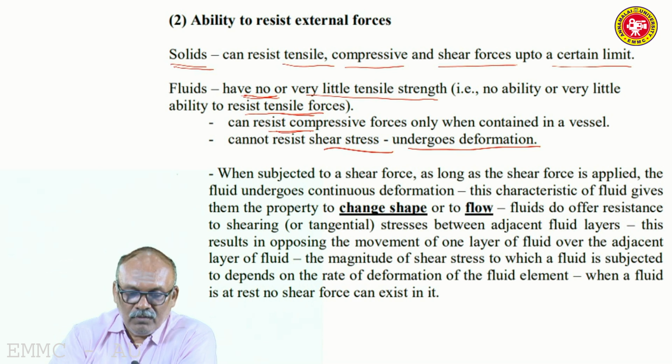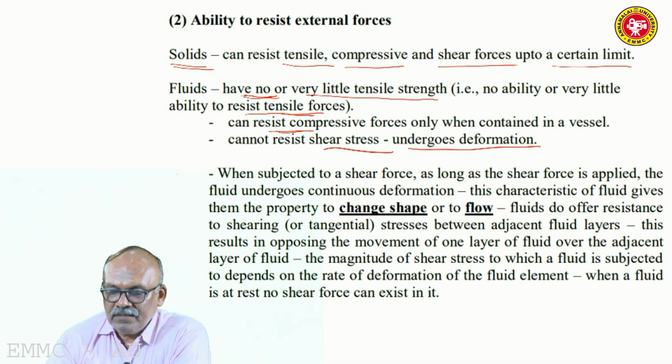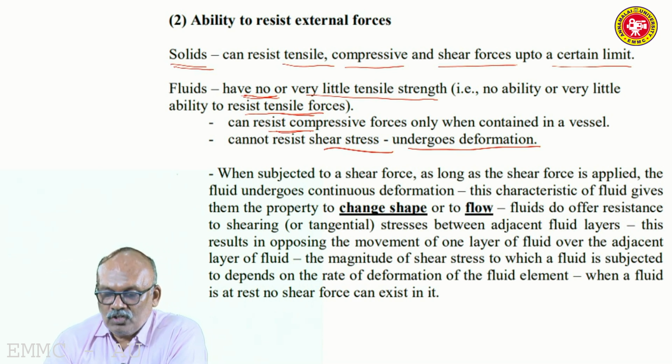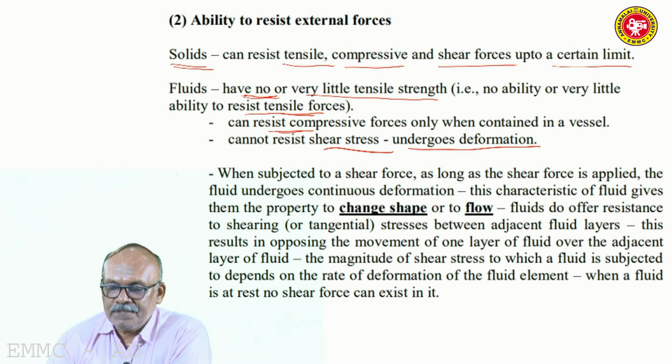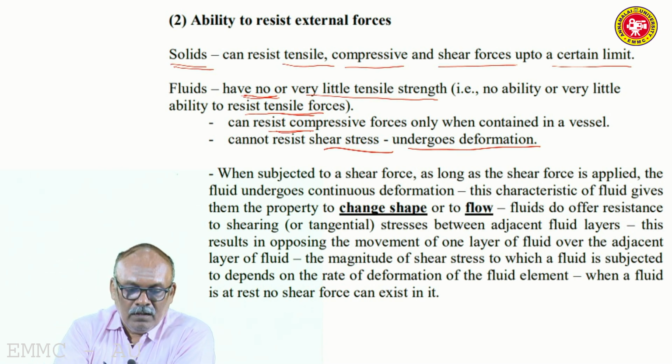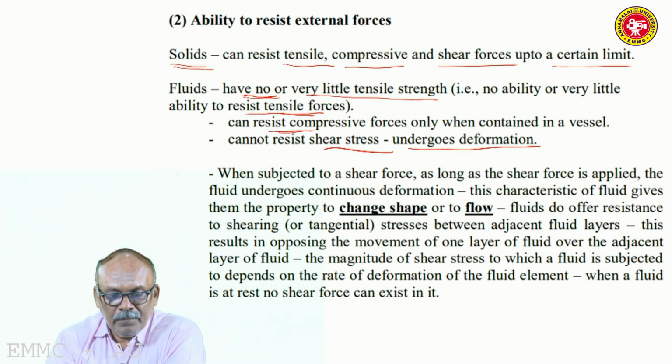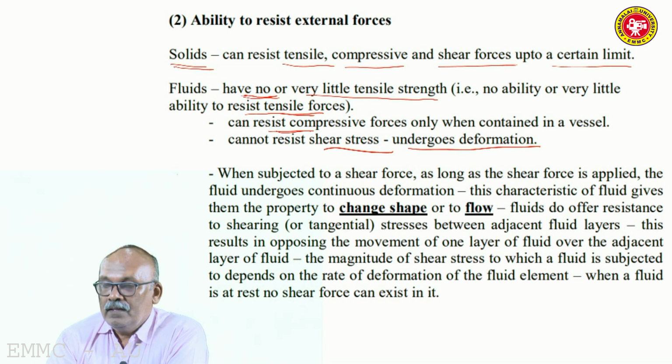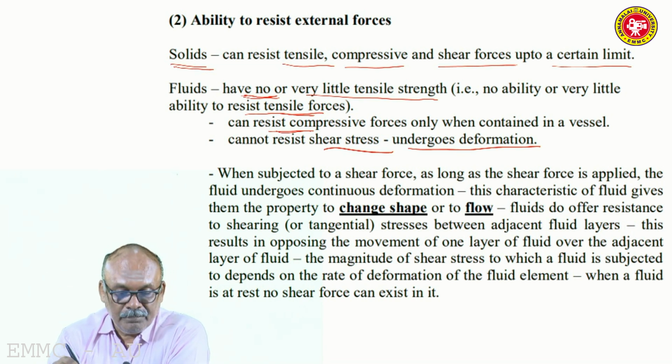Whereas fluids have no or very little tensile strength. So later on we will talk about surface tension of a liquid. That is the very little tensile strength the liquids possess. Again, it is a surface phenomenon. Whereas the fluids can resist compressive forces only when stored in a vessel. They cannot resist shear stress and they undergo deformation.